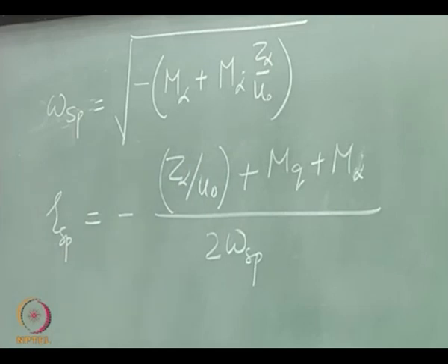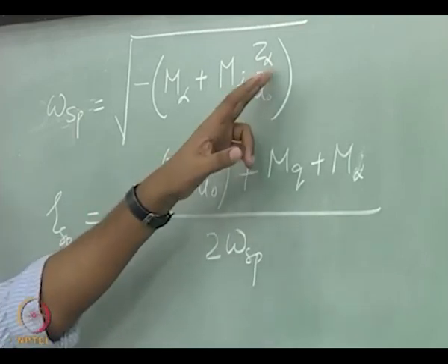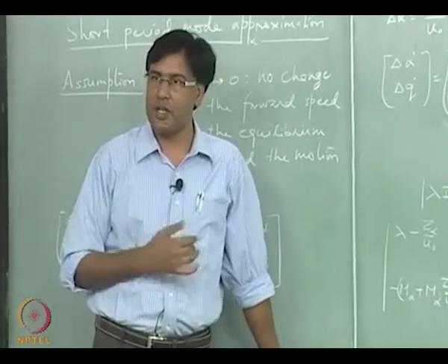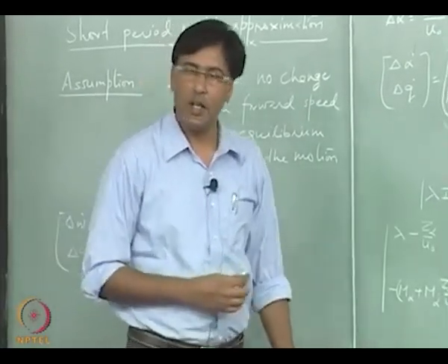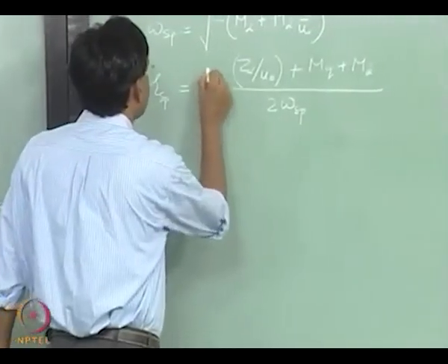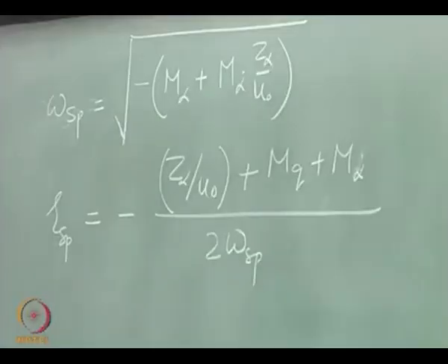So, earlier when we talked about the pure pitching motion, we did not have this Z_alpha term, right. Of course, because the aircraft was constrained only to have pure pitching motion and not any other motion. So, that was an assumption that we used there.